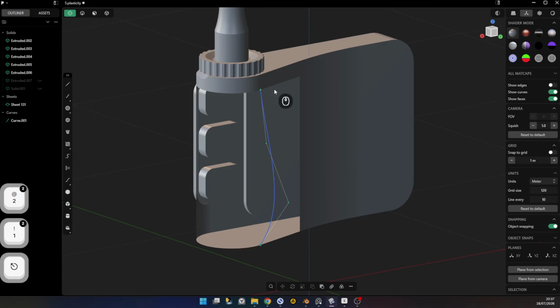And remember our analogy about simpler modeling, how a lot of our issue is going to be where we're going to ask software to do the impossible. With surfacing, 95% of your issue is going to be that as well, where you are basically asking the software to do two contradicting tasks.